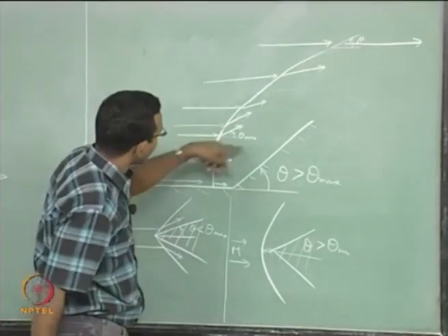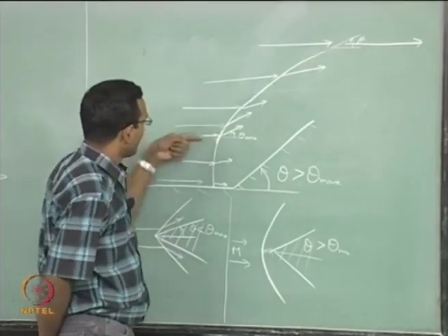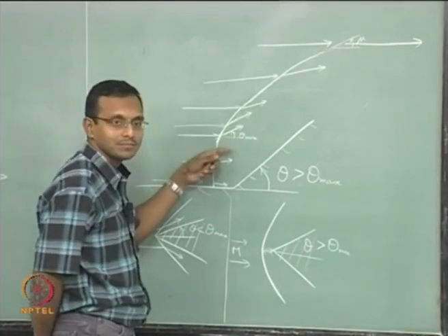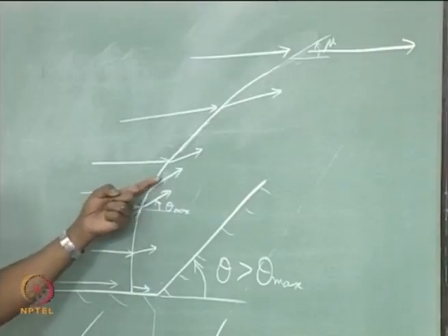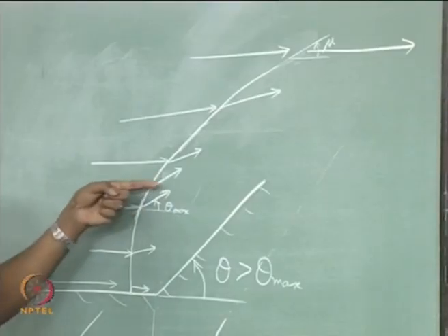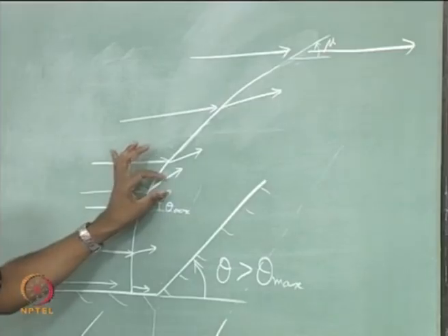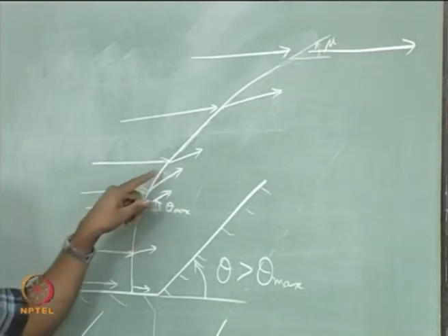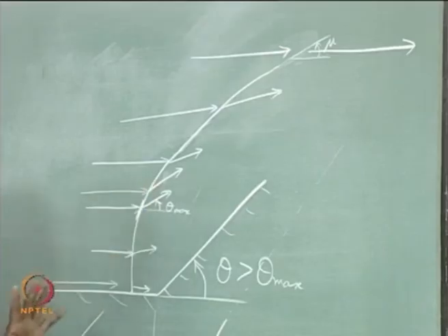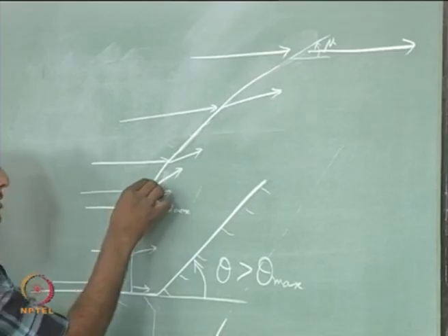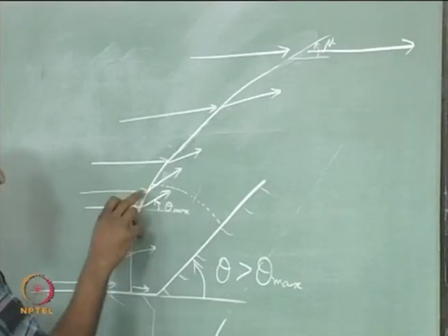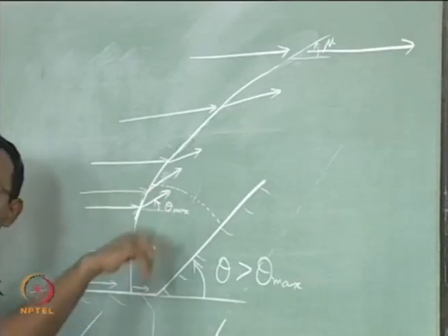Now, if I look at this area, this one line has the highest theta, on both sides it has lower theta, which means this one will want to go crash into this streamline, that is, there is extra compression happening after the shock. Okay. There is something more happening after the shock here. Okay. Such things are also possible. In most cases, somewhere up to here will be subsonic flow inside this region.